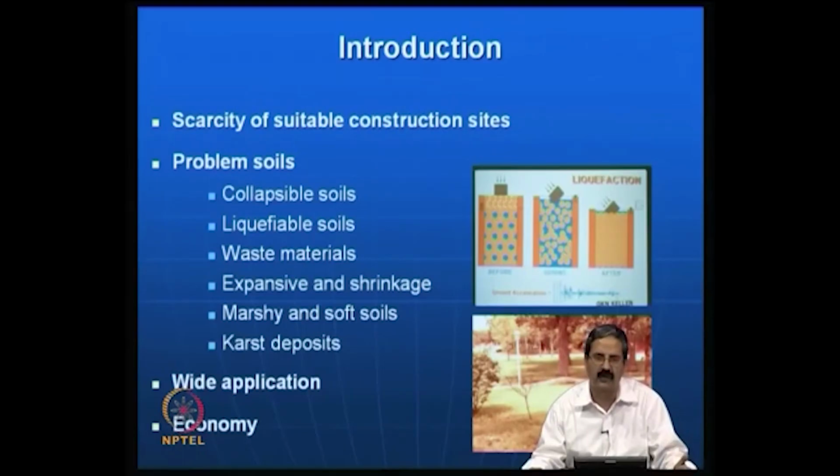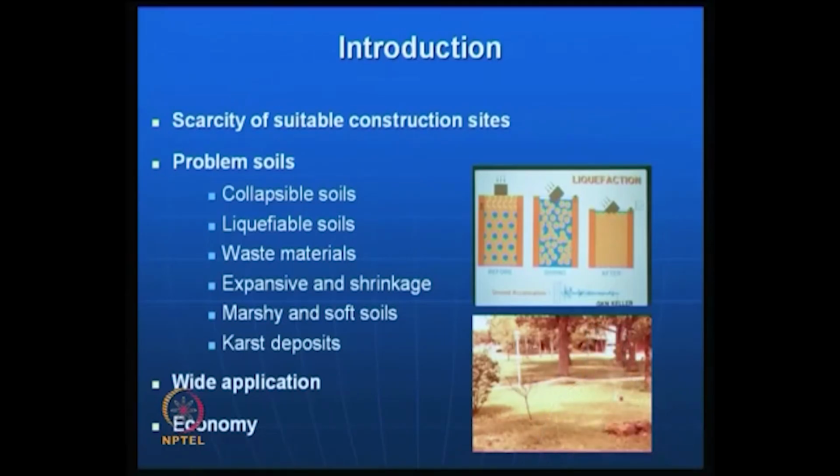We do not know how it forms, but when there is contact of soil with water, all that soil is lost and suddenly you find a cavity. So, this is a very big risk. You need to fill up those voids or gaps and then see that the bearing capacity of the soil is there to the extent that we need, and also settlements are minimum.